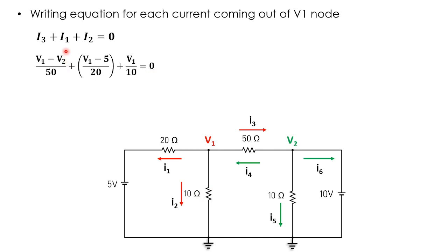Now, if we can find out the value of V2 here, we can directly calculate the value of V1. In this particular circuit, the value of V2 is directly known to us, and that is equal to 10 volts. How? This is the ground potential, right? So the potential here will be 0. And now if I go from this point to V2, in this direction from this path, the only component that I can see here is the 10 volt source. Now it is either in the supporting polarity or the opposing polarity. I will discuss this supporting and opposing polarity in the upcoming slides. Currently it is in the supporting polarity because we are going from minus to plus here. So we will add 10 volts and then we will reach V2. So V2 is basically at 10 volts potential.